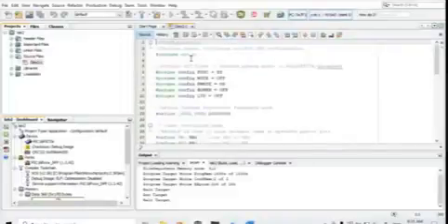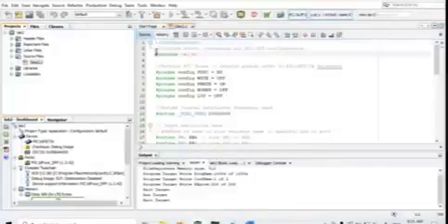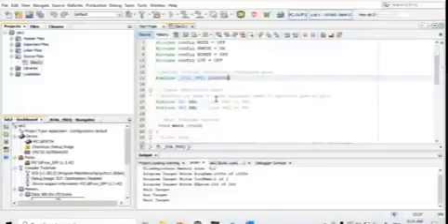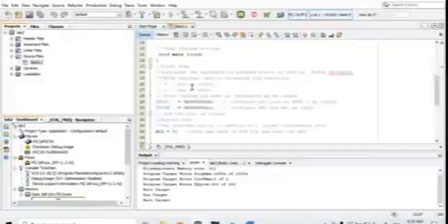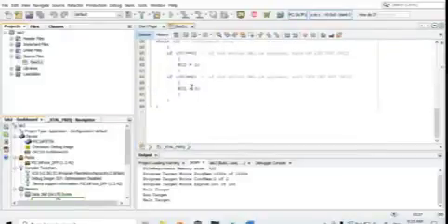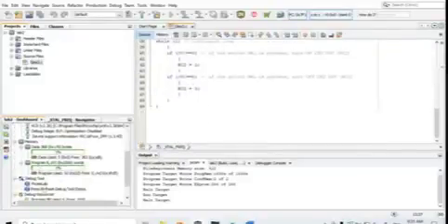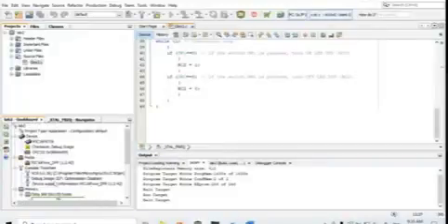Same code from the module, and then we write it here, and then you need to add the important structure, which is the first one, and then the clock configuration, and then this one. You can see we rename it. We define SW1 as RB0, and so on. Make sure PICSimLab here should be PICSimLab, and then the compiler must be XC8.